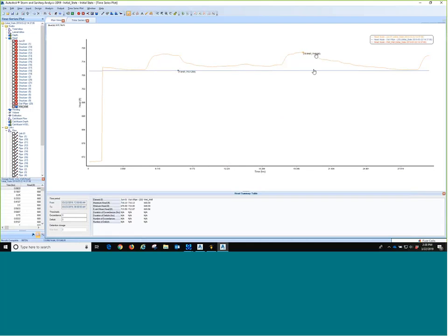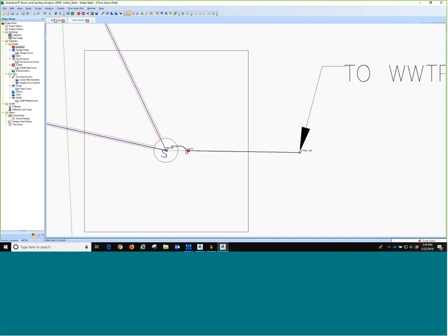So it looks like I've got a head loss for that flow rate of 63 gallons per minute. I have a dynamic head loss of about 8 feet of head. And then I need to push a total head from the difference of my wet well elevation down here all the way to the top. I can't remember what that came out to. Not a massive number, but I kind of came up with a rule of thumb.